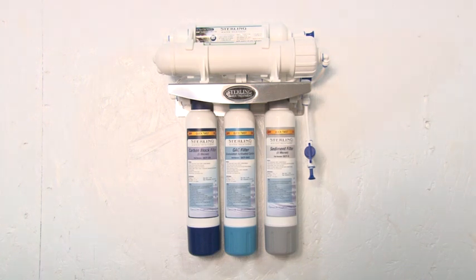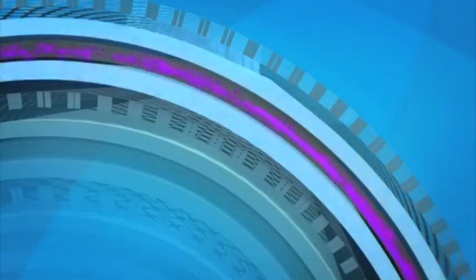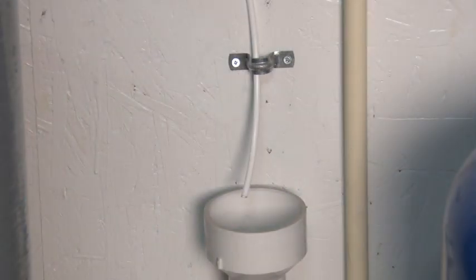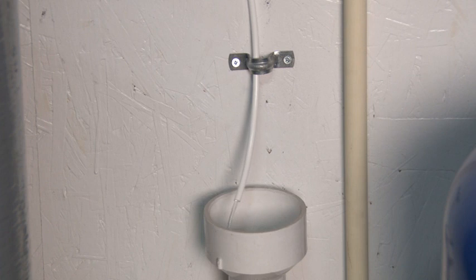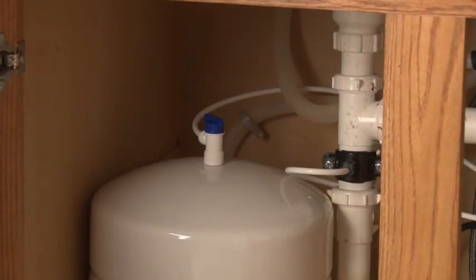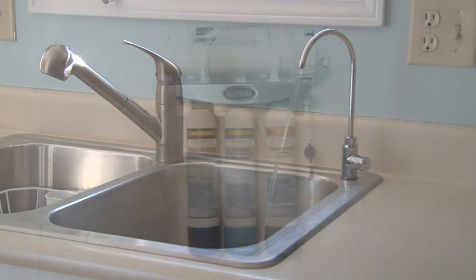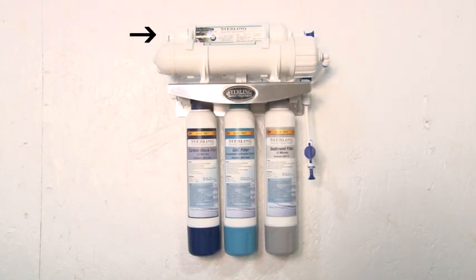Under pressure, water is forced through the membrane. Molecule by molecule, the water slowly moves through the membrane. Most of the dissolved solids in the water cannot penetrate the membrane and are washed down the drain. Finished water that has passed through the membrane is stored in the pressurized tank. When water is drawn from the RO faucet, it passes from the storage tank through the final polishing filter.